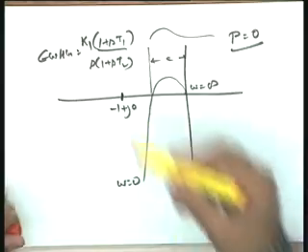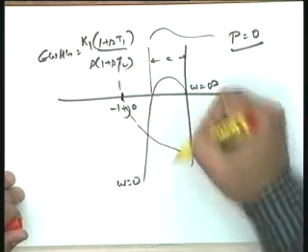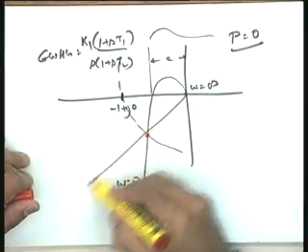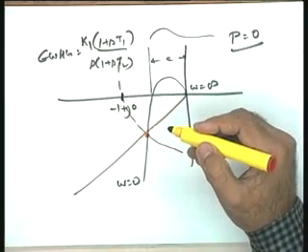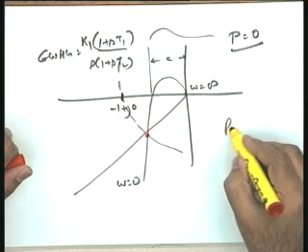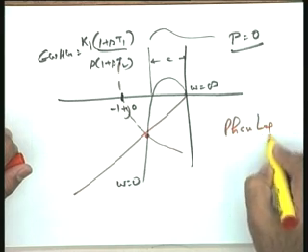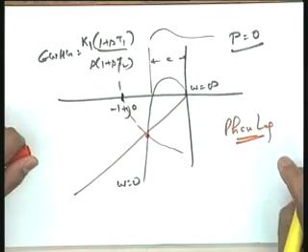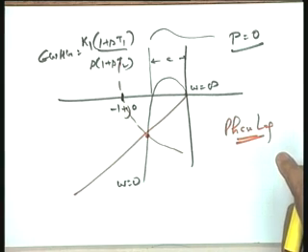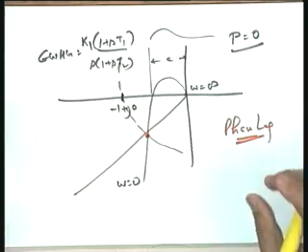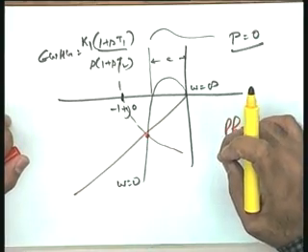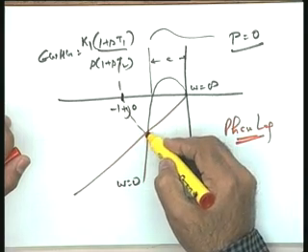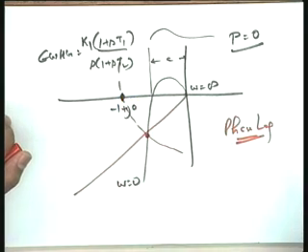Consider the phase margin. You see, this is the point, take this angle, you see how much phase lag you can add. Phase lag is the term I will use which creates instability. You have seen dead time introduces phase lag, which is a problem which creates instability. So the question is how much phase lag can be added to the system so that this particular point passes through minus 1 plus j0 point.